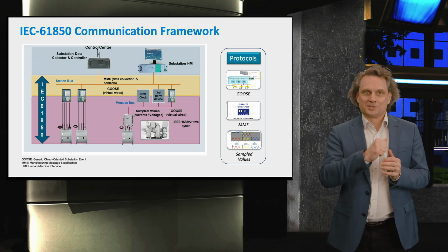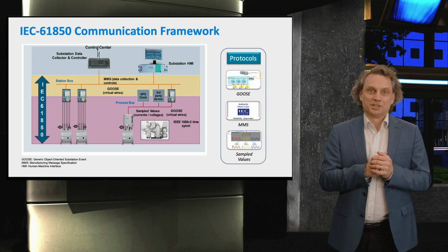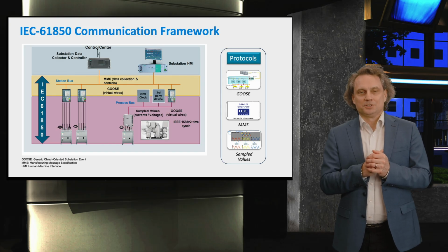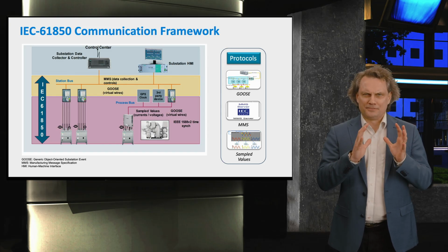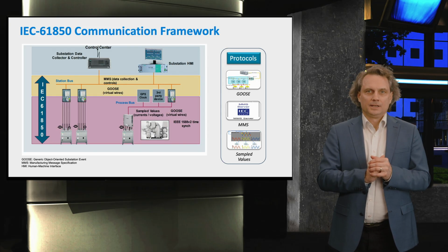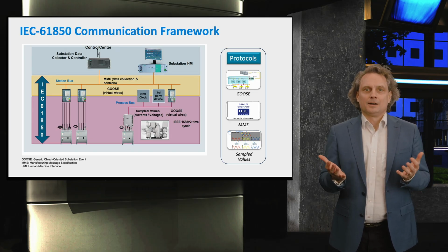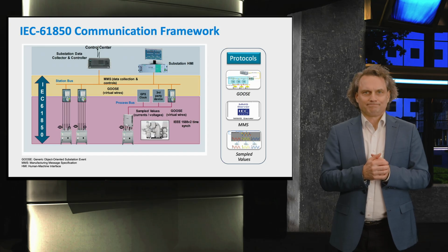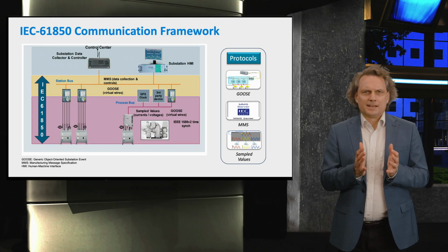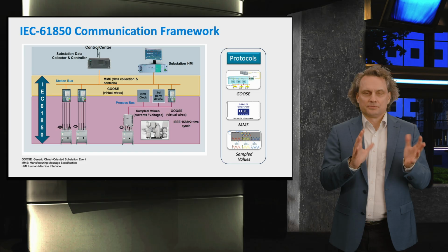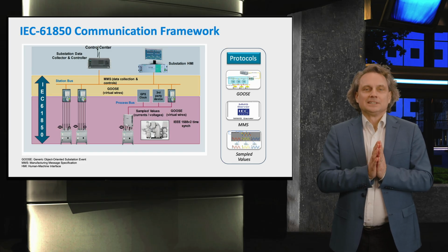The first one of interest is called GOOSE, Generic Object-Oriented Substation Event, and is a very fast protocol. It gives asynchronous messages that can be used as alarm messages or as commands. GOOSE has a guaranteed maximum latency of 4 milliseconds.